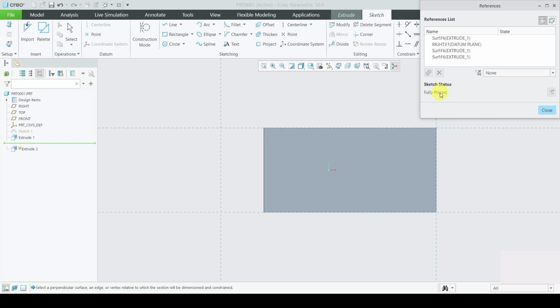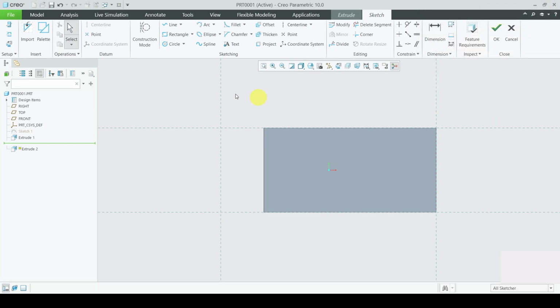So what does it mean? It means that if you want to select this reference and this reference while creating your sketch, then these are okay in order to proceed. So you will use another rectangle and select this corner of the rectangle first, and then say this is the border which you want to create a cut out of.